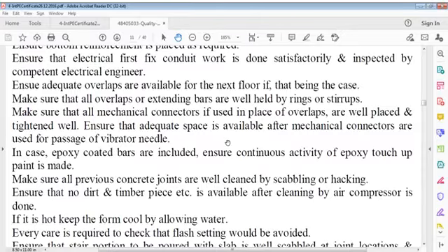Yes, before being lost, let me complete this statement because there's some problem in the computer. Then we have to take care of epoxy coated bars if we have used them, and we cannot connect cathodic protection to an epoxy coated bar. We have to keep that in mind.